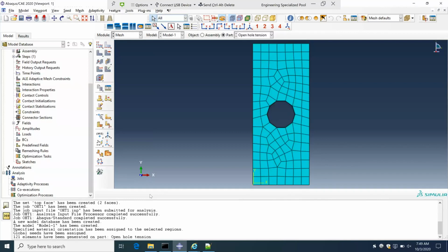Ow. So it looks like a very irregular arrangement of elements. And if you were to just perform your analysis on this with the appropriate boundary conditions, you will see a stress or strain distribution that is not so regular. And as you can see, this model is symmetric. It should be symmetric, right? So the mesh we want as symmetric as possible, depending on the geometry.